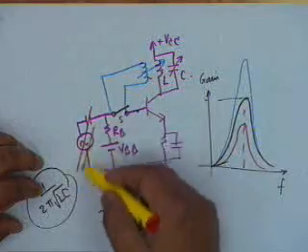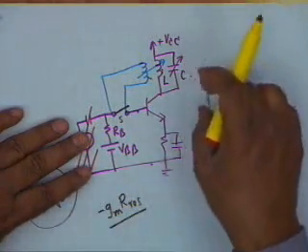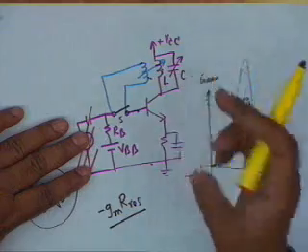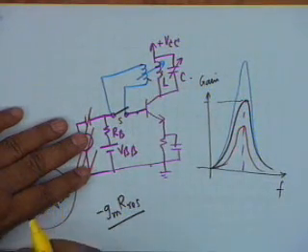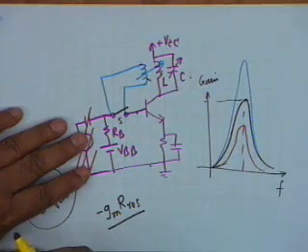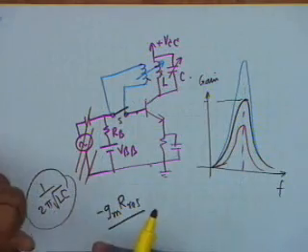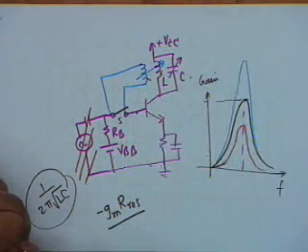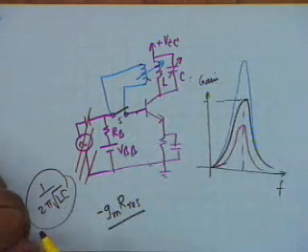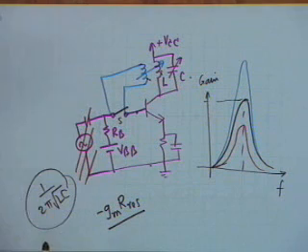In other words, you shall not require this Vi. This source shall not be required. If you couple an oscilloscope from here, you shall see pure sine waves on the oscilloscope. This is how one generates sinusoidal frequencies. Such an oscillator is called a tuned oscillator, because there is a tuned circuit, a resonant circuit here, all right. A tuned circuit oscillator is not practicable at low frequencies like audio frequency.